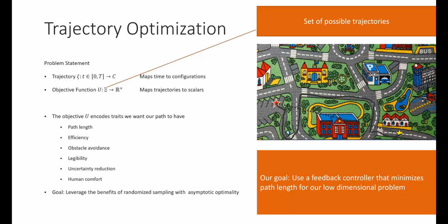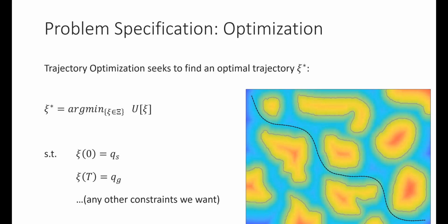That's something that's going to be highly dependent on the cost function that you specify. You could set up a cost function such that it has a penalty of 1 million for not reaching the goal state in time, in which case, if all of your other components of your cost function have relatively low ceilings, then you'll know that there's no way this thing could have gone over 1 million if I didn't violate this constraint of mine. So that's totally something that you have to define yourself. And you also get no guarantees with this, because it's not a global or optimal solution. It's doing a local solution based on your initial guess of the solution.